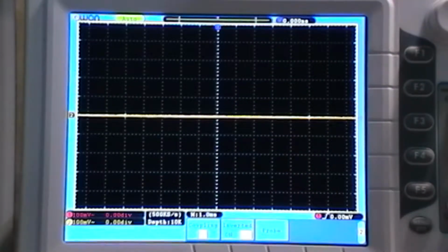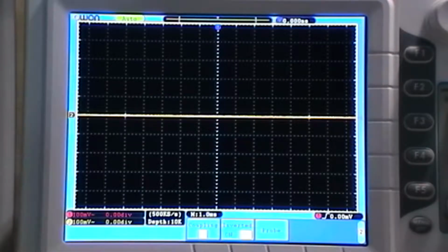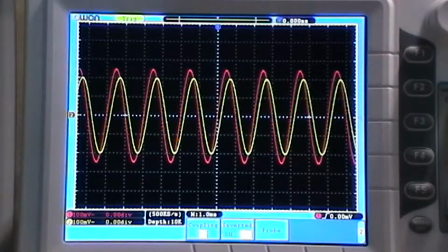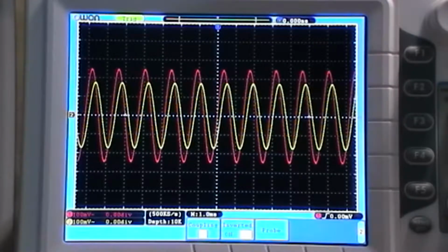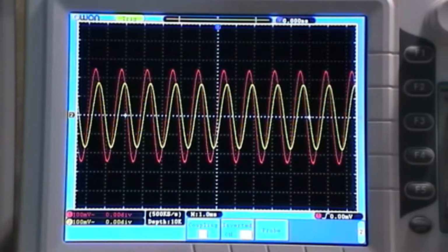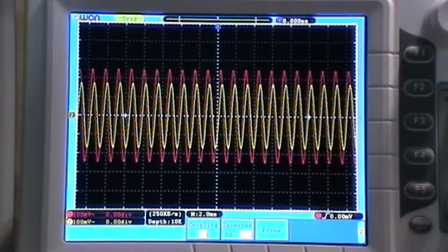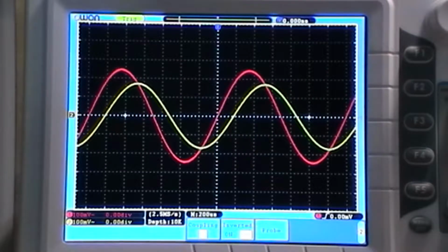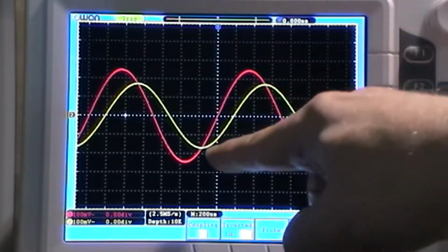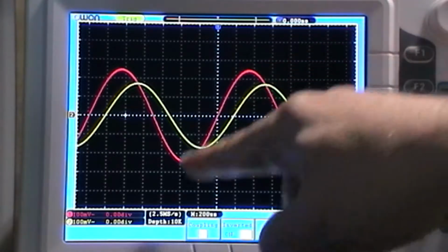Right, so I'm going to leave it on 500 hertz, and I'm just going to turn it on and see what it gives me. Well, it looks like it's already attenuating, because actually with a 220 nanofarad it starts to attenuate at about 723, so that's at 720 hertz. So I suppose the thing is that it's 3 dB below my original.